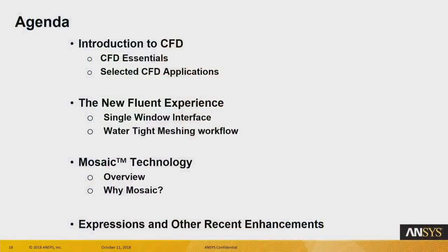Then I'm especially excited to tell you about the new Fluent experience that has been brought by the Ansys development team in the version 19.2. You can set up, solve, and post-process your problem in a single graphic user interface in Fluent, starting from importing the geometry, creating the surface mesh, generating the volume mesh in the brand new Mosaic Technology, and I'll explain what that is, and then setting up and solving the problem without having to use different applications, save the files, read them again, and so on and so forth that our users had to do in the past.